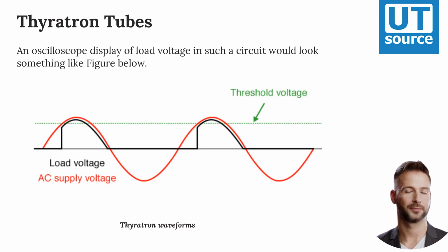an AC-powered load must also periodically halt. This brief pause of current between half cycles gives the tube's gas time to cool, letting it return to its normal off state. Conduction may resume only if enough voltage is applied by the AC power source, some other time in the wave's cycle, and if the DC control voltage allows it.